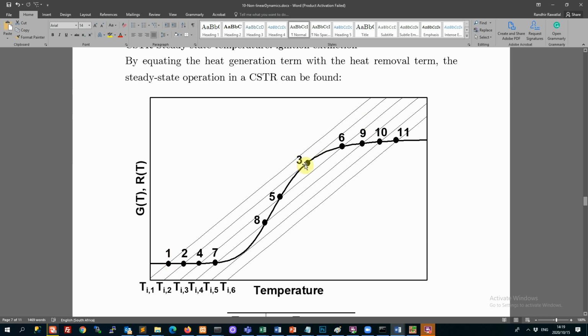So that's an important feature for us to understand. We need to understand that our inlet temperature is not some arbitrary number that we can just go and specify. That inlet temperature has to be carefully chosen because the thermodynamics of the system are such that there are specific regions down here which influence our operation and what kind of steady state is available to us. It can totally upset our attempt to control that reactor if we have the wrong operating parameters. So we might stray across an extinction point and kill the reaction.